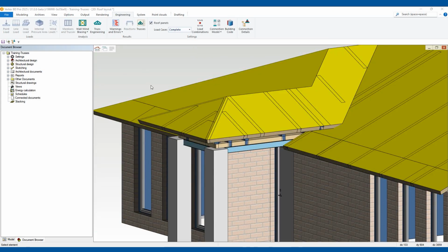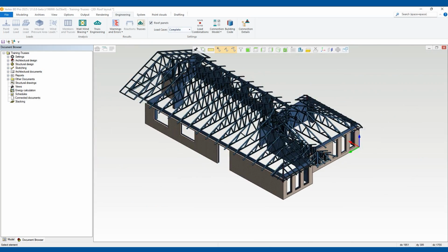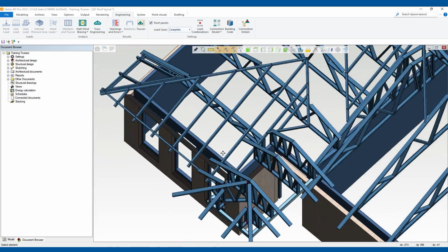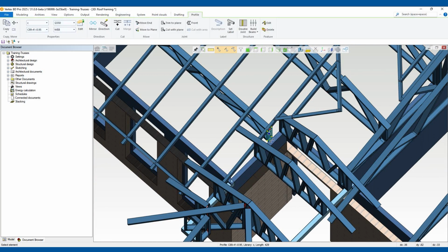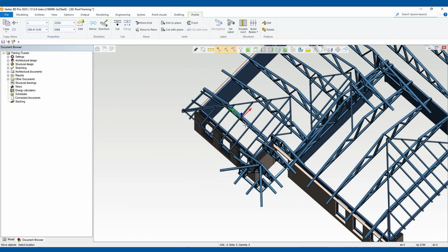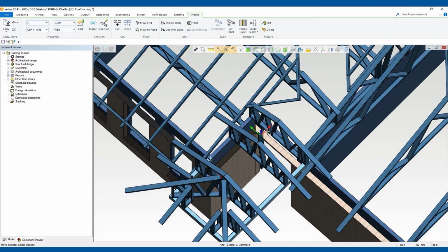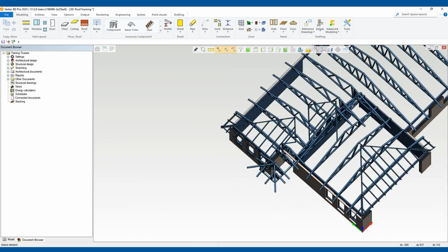Which I forgot about. So this truss is not being supported. You can go and fix the envelopes and everything and put plane extensions, or you can just move that end web like 50 mil or something, so it's sitting on there.